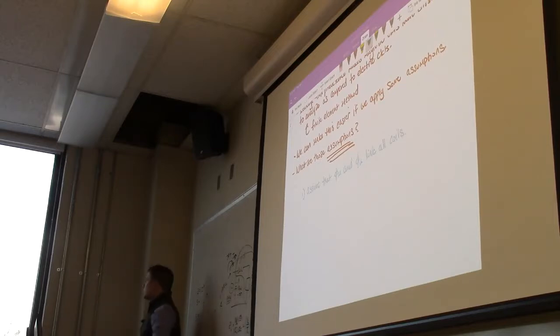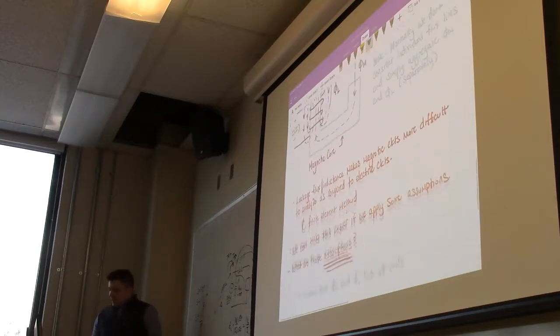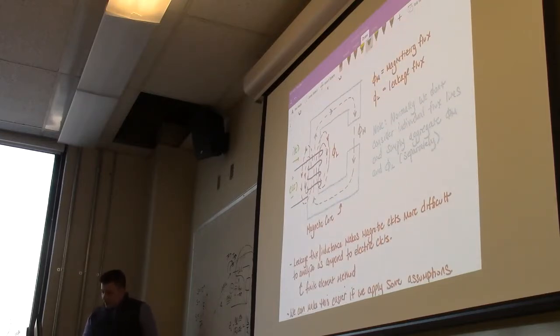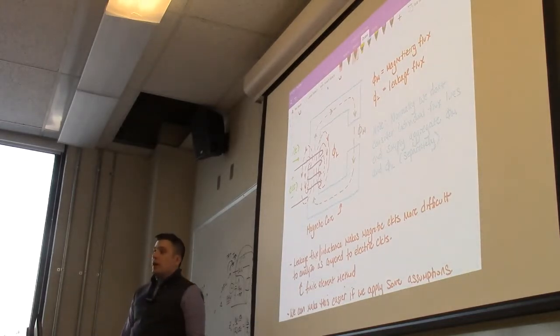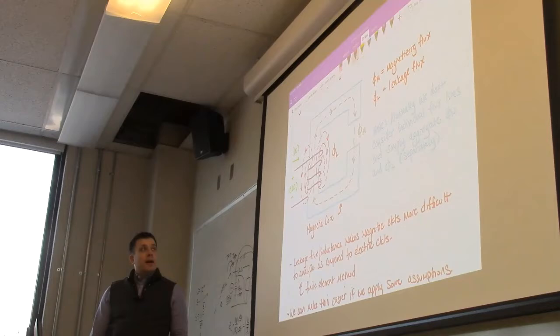First, we're going to assume that the magnetizing and the leakage inductance link all the coils, because one thing which I didn't draw here is, right, you can have little mini leakage loops which don't necessarily, here we have 4 turns, that don't necessarily connect all 4 of the coils with one another, right?